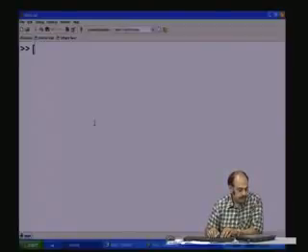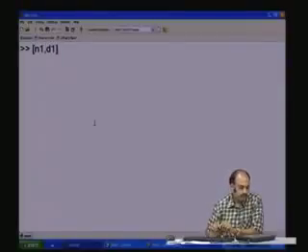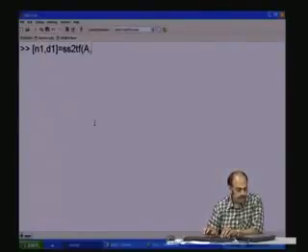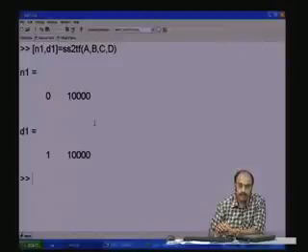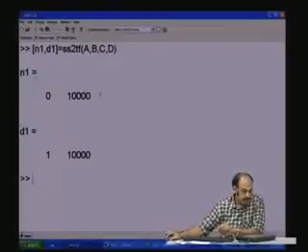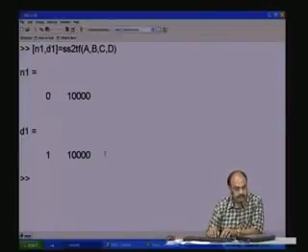do this particular conversion. Let me have a numerator polynomial n1 and a denominator polynomial d1 of the transfer function, which should be obtained after the conversion, SS to TF, state space to transfer function, and we have the A, B, C, D matrices. So, this A, B, C, D matrices should get converted to the numerator polynomial and denominator polynomial. This is the numerator polynomial as a function of S, this is the denominator polynomial as a function of S. Of course, it does not look like a transfer function.